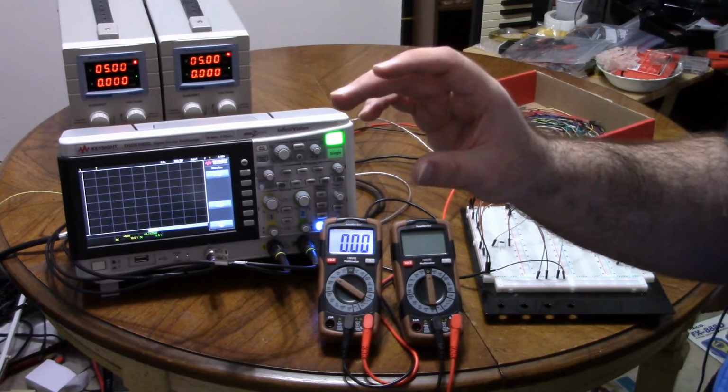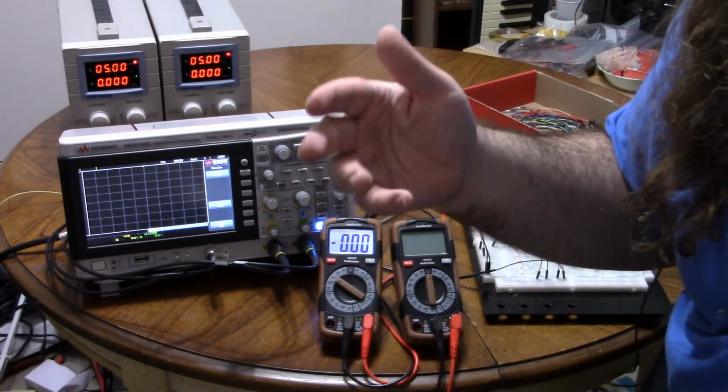You are tricking the system. We think of the ground, the reference voltage, the 0, we see 0, that's the lowest point. That's the thing that's not intuitive. You get into that rut of thinking that you have your power supply and you go down to 0. And that's how your circuit works. But 0 is whatever we decide it is. It's a reference voltage. It can be anything.